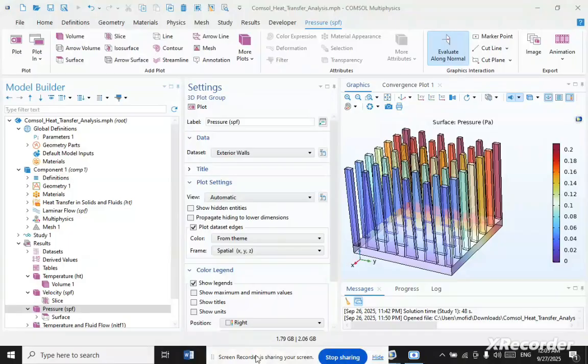The sixth conclusion is a pin-fin height variation along the channel length must be arranged in an increasing pattern, as the decreasing pattern has shown inferior performance compared with the growing design. And last but not least, better flow mixing has resulted from the stepped arrangement of pin-fins along the length and the breadth of the channel than from the stepped arrangement along the channel length alone.